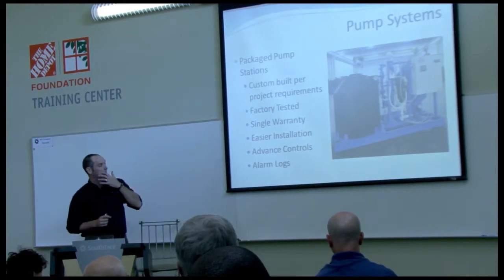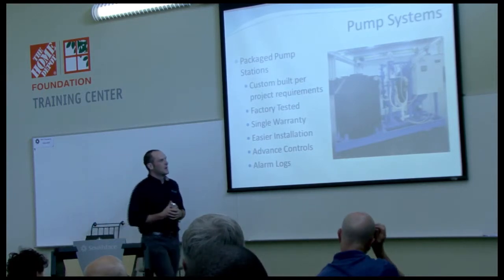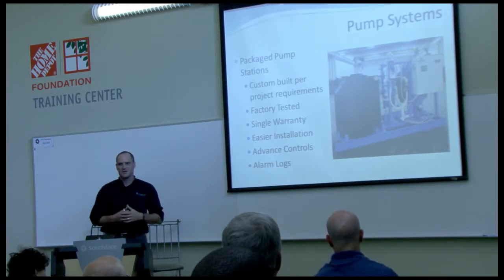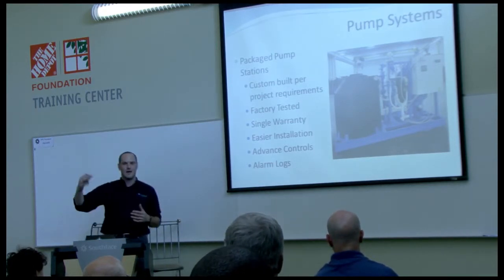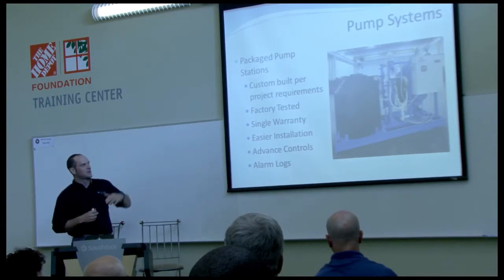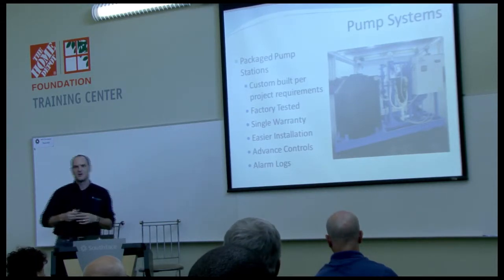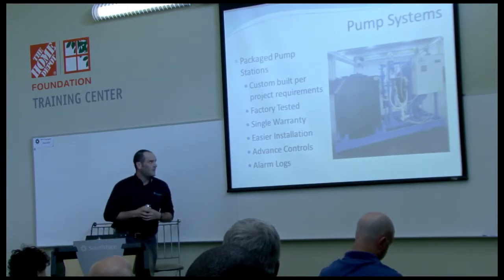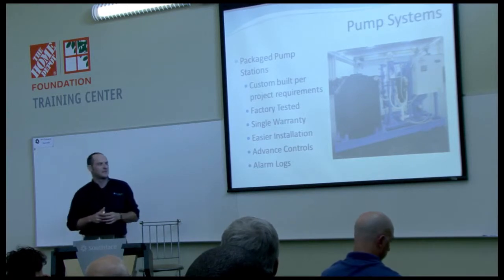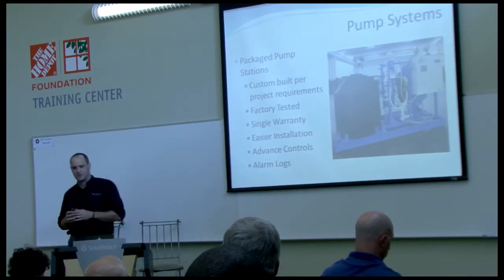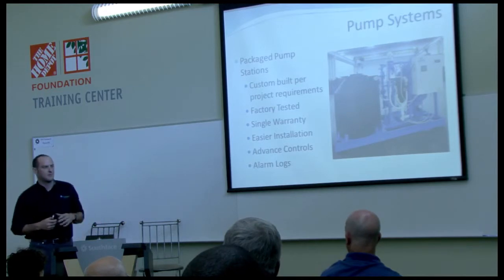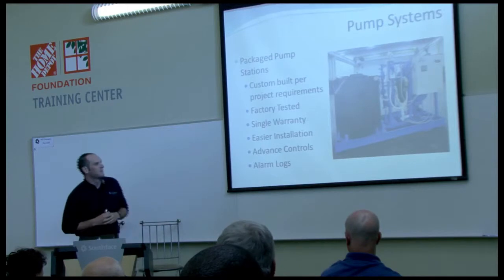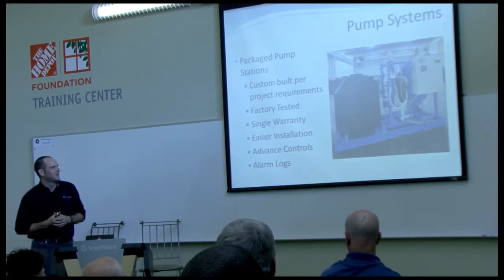So with these systems, again, they're generally more expensive because you have so much more capability with the controls. They have alarm logs. If you have an alarm, a low-level alarm, high-level alarm, burst pipe, whatever, you can go into the system and see, most of them go back 2 years, what type of alarms you've had, so they help you troubleshoot the system. They're factory tested before they leave the site, so it's built in a controlled environment and tested to its full capability before it goes to the site. So theoretically, it should be an easier installation because you get there, you plumb up the skid, and get it running.